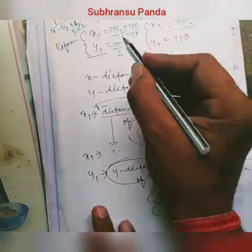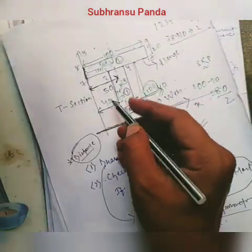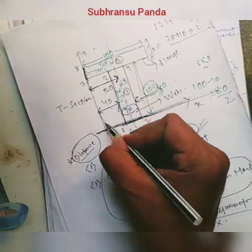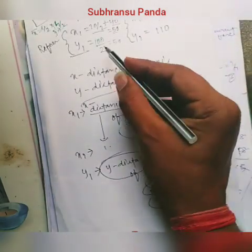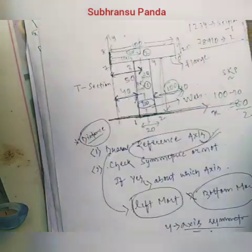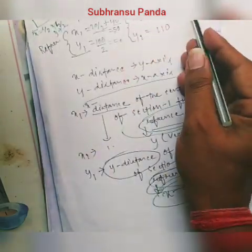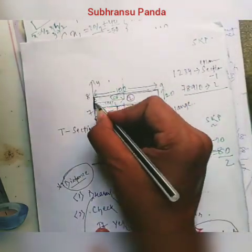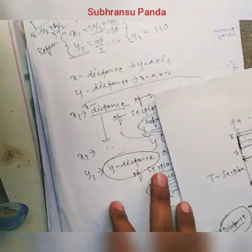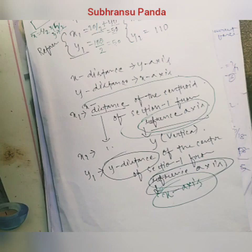So x1 is 20 by 2 plus 40, because x1 is not touching the reference axis, so 40 is added here, plus 10, this is 150. Similarly y1 is already touching the reference axis, so directly I am writing here 50. Section 2 is touching the reference axis, so x2 equals 50 and y2 equals 110.